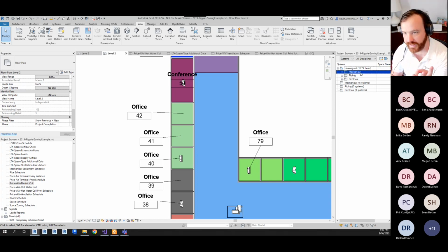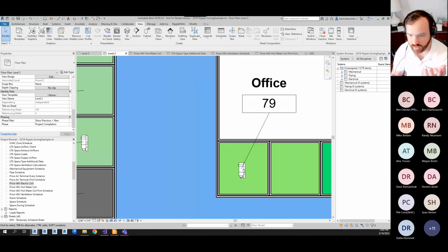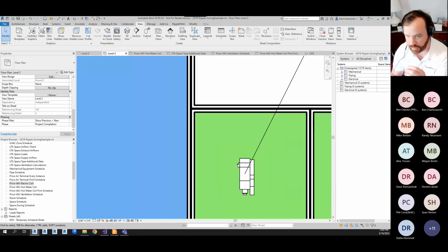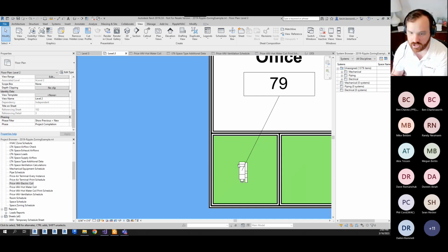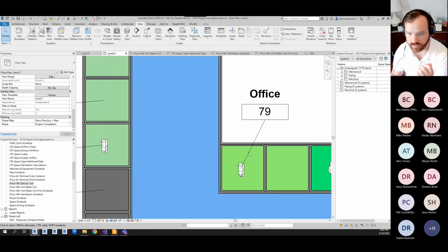Okay. And what's worse is each heating water is going to have 3 unassigned systems: an air system, a hydronic supply, and a hydronic return. I guess that is a good thing to point out, that the connectors are all set up right. The pressure drop is assigned to the connectors correctly. So you've got half the pressure drop on each connector. So you can do piping pressure loss calculations with these VAVs.